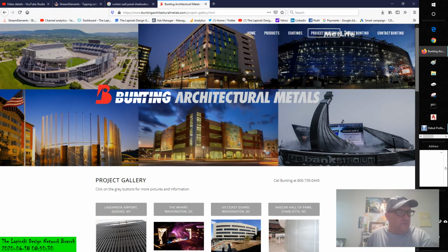Our last example shows how metal louvers can be embedded in a curtain panel family. The image shown here is a panel developed with a nested generic model. The louver fins are arranged in a parametric array within the generic model. And I could show you how to array, but that's a whole other story. And when you get to that, believe it or not, this instructional series is kind of unique in how it's set up. It'll introduce things when they need to be introduced.